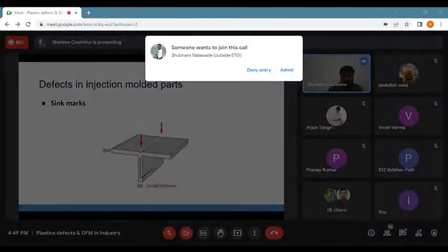But if this rib is not designed properly, there's a particular way, there's a particular calculation where a rib is designed in a particular way. Like if this is the lower part, this is the thickness, okay, here we draw a circle, and there are a couple of calculations that you need to ensure that this circle touches the fillets that you are going to give to your rib. That gets a little more dense, so I'll not cover it in this one. But yes, you need to perform a proper calculation.